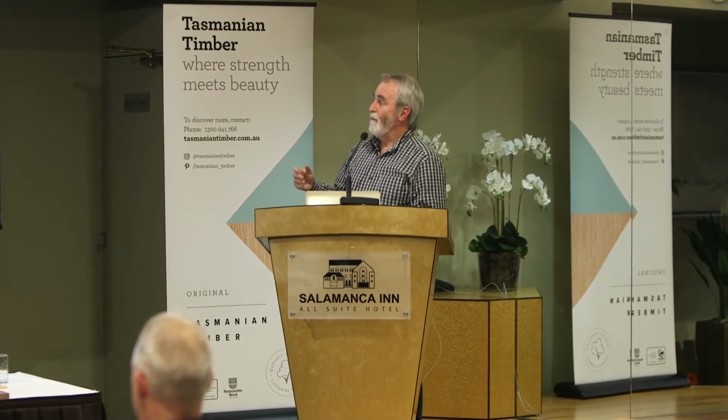Fire resistance in the codes, the major ones we're looking at are the basic fire indices that are required, I think clause C1.10, which calls up levels of fire resistance, spread of flame, smoke developed indexes, etc. The thing with timber is that timber's generally all bunched together. It doesn't matter how dense or not dense the wood is.